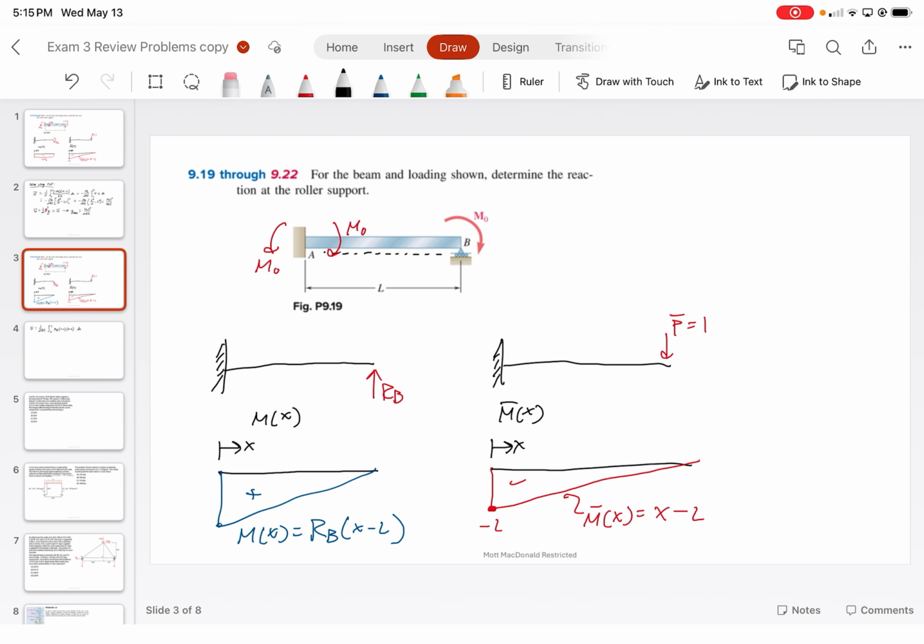Now we can technically change the assumption about P bar, right? In this case, we don't need to. The math will just show us the direction. So we're assuming that from this case, due to the vertical reaction upwards from RB, that it's deflecting downwards. So for our answer, we should technically get a negative value for the deflection. All right? Does that make sense, what I'm trying to get at?